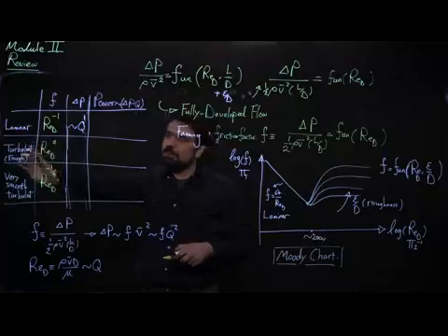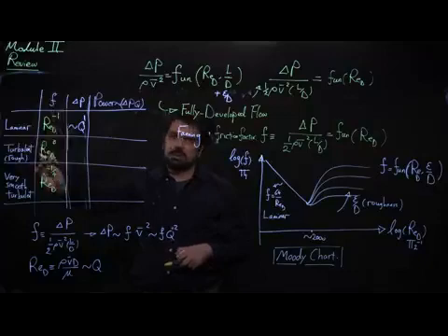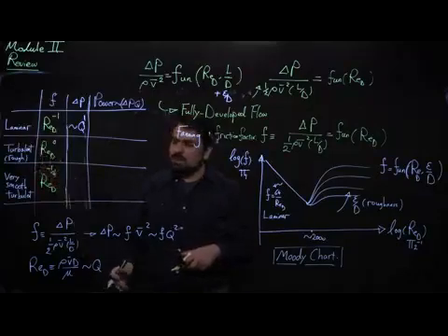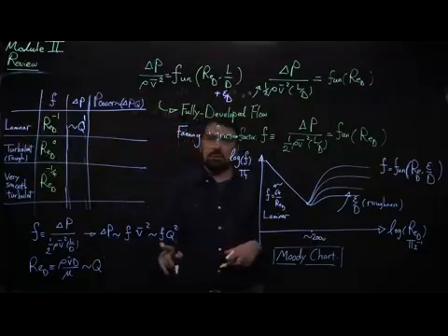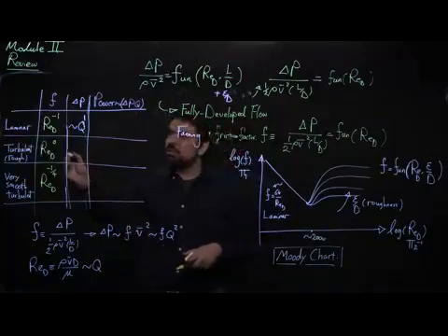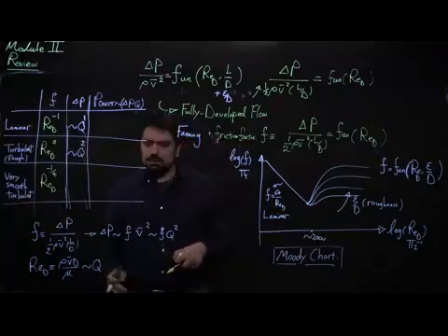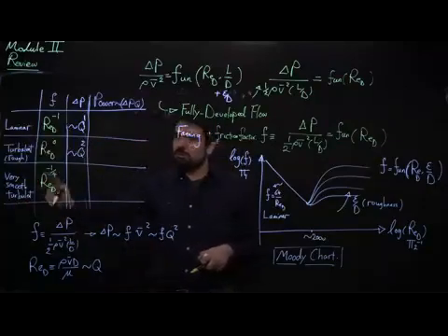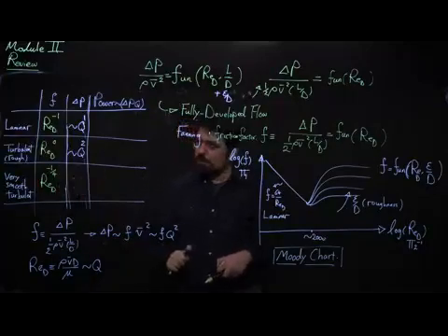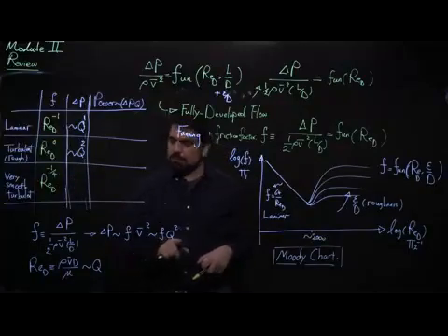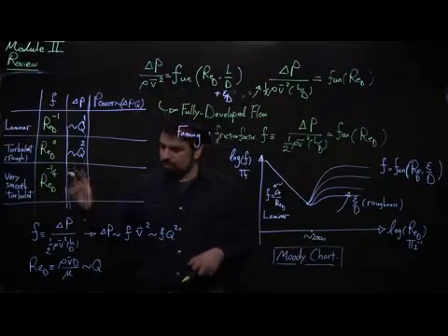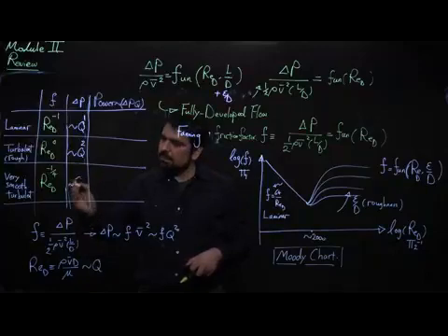In the turbulent regime, however, as you increase the flow rate, Reynolds increases, but the friction factor is not changing. Friction factor remains constant, which tells me that delta P will go as a constant friction factor multiplied by Q squared. So delta P really goes as Q to the power of 2. However, for very smooth turbulent pipes, friction factor goes as Reynolds to the power of -1/4, which means that it goes as Q to the power of -1/4. Multiplied by Q to the power of 2, that gives a relationship for delta P with Q, which is Q to the power of 7/4.